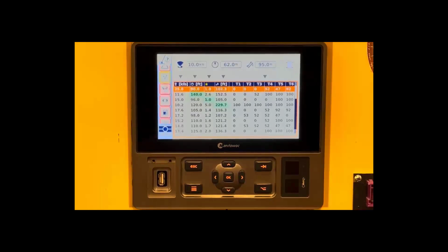The time, we have a best of 1, which is the quickest. For the boom length, it shows 229.7 highlighted, which means that would be the longest boom configuration. And if we scroll down, we see for the load, we have 25,000 pounds highlighted green, which is basically telling us this is the highest capacity on this list. So now we can make our decision on what configuration we want.